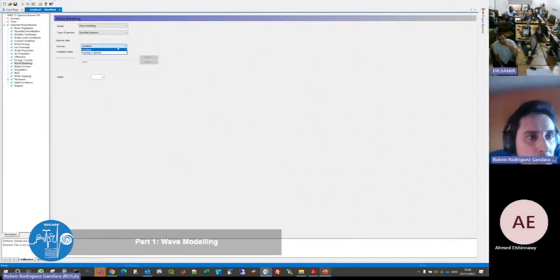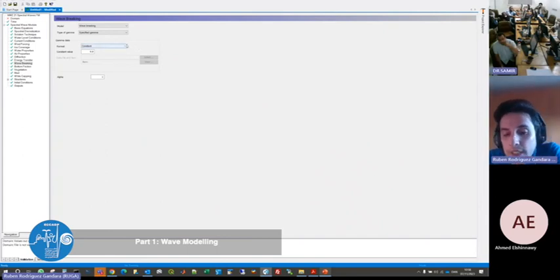If you're talking about constant and varying domain, if you set this option to constant, in every single node within your mesh, in every single node where the computation is carried out, it will always consider a gamma value of 0.8. If you go for the varying domain, you will have to provide to MIKE a map. It doesn't have to have the same resolution or shape as your mesh, but for sure it has to cover the entire domain of your mesh.